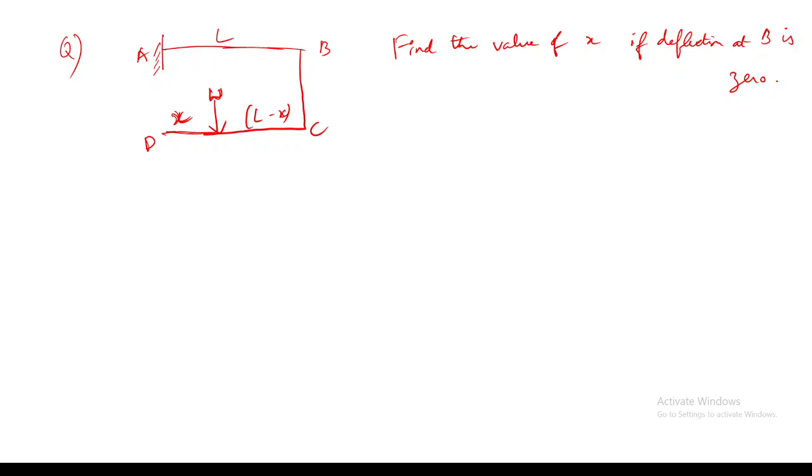We transfer the load to B. We have already seen this kind of rod questions during our SFD and BMD diagrams, when we were learning SFD and BMD. Similar to that, you can transfer the loads from D to C to A to B. So directly you transfer these loads W to AB, and say what the load looks like for this AB section.